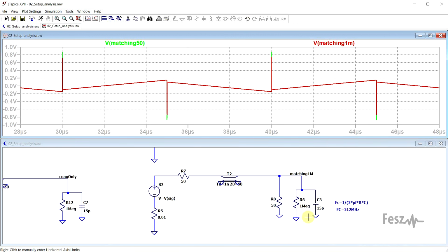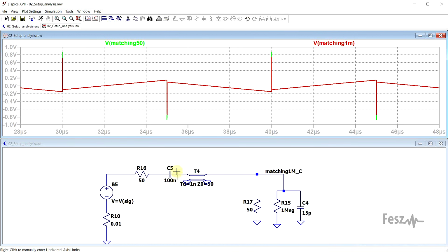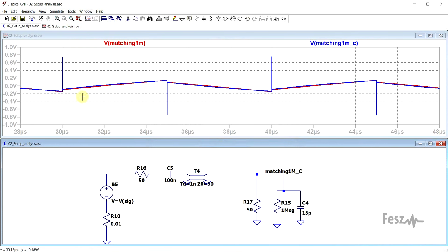But anyway, final thing to mention is that while this sort of setup works, as it stands, you're still introducing a 100 ohms in parallel with the circuit. So this will draw quite a bit of DC current in case you're probing higher voltages. Now, in case you just want to observe the AC ripple and noise, you can of course add a capacitor in series and eliminate the DC component. This sort of setup should however be done with care, since if the capacitor is too small, then the signal again will be distorted.